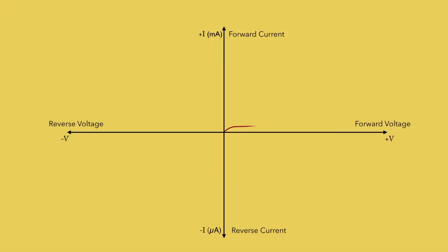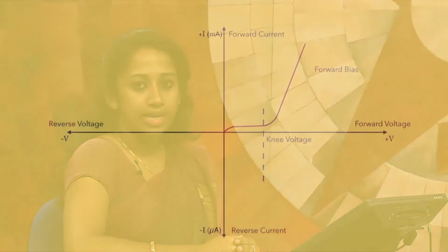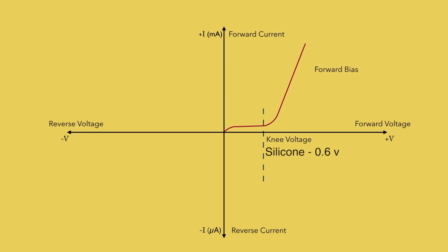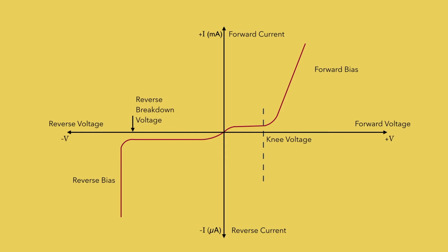Diode rectifiers rely on diodes for their operation. Diodes are devices that only pass current in one direction. As we know, the diode has a characteristic something like that shown in this figure. In the forward direction, a small voltage is required across the diode before it conducts, which is the turn-on voltage. The actual voltage depends on the type of diode rectifier and the material used. For a standard silicon diode rectifier, this turn-on voltage is around 0.6 volt, and for germanium it is around 0.3 volts. In the reverse direction, the diode rectifier will ultimately break down. This is a property of the diode that we are using in rectifiers.